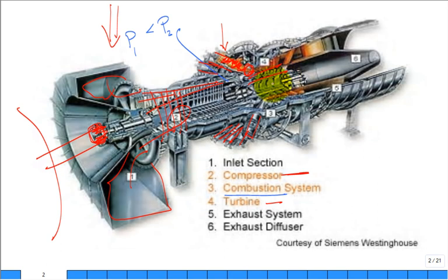Now, they often are broken into two sections for the turbine. One section of the turbine needs to extract enough work to run the compressor, and it'll come back on a shaft to run the compressor. That's because the compressor is going to take a lot of mechanical power. And then maybe a second set, or maybe there's a gearing system, depending on the design. A second set of expansion would be connected to this shaft that is to develop power and provide it external to the gas turbine. That's a second set of turbine blades to expand it. So there you get the mechanical power.